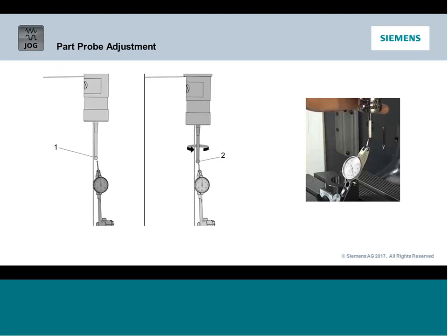Now, a lot of guys overlook this step when starting to use part probes. And that's, I want to make sure that the ruby or my stylus is running concentric to my spindle. Now, all these are adjustable on all these different manufacturers of probes, usually a couple set screws, but you do want to make sure that you spin the spindle, you indicate in, and you get it as close as possible. The cycles are certainly set up to compensate for any run out, but why add error where we don't need to? That's always been kind of my rule of thought. So get it close. The cycle will compensate for any inaccuracy that might be there. You know, you're never going to get this stuff perfect, but you certainly don't want a probe that's got 10th out run out in it.